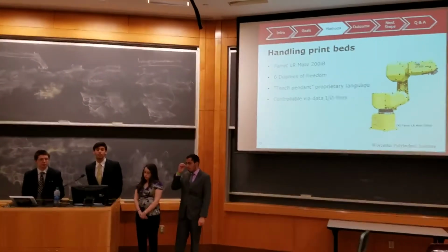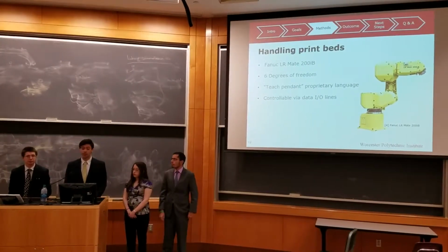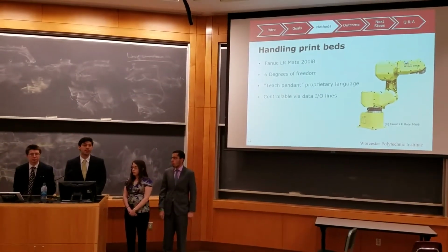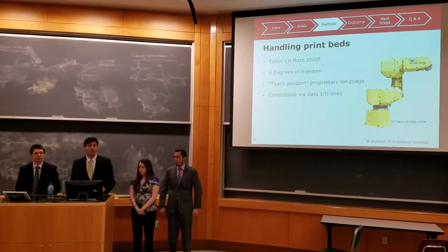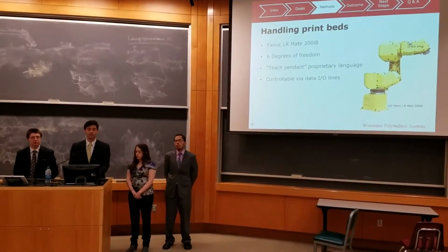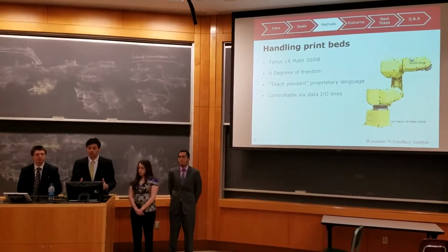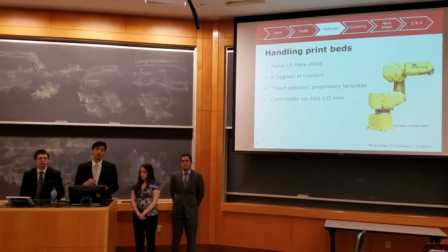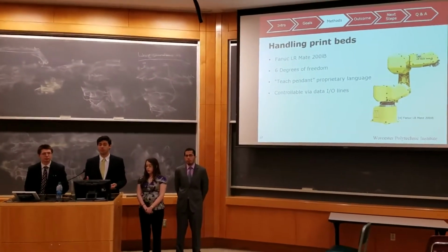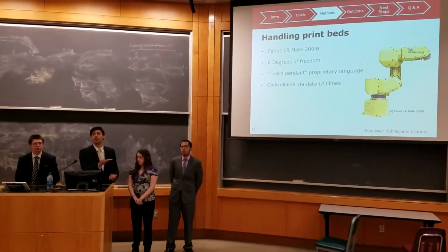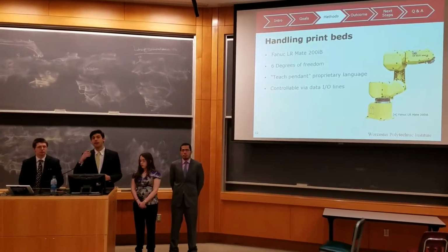So how we physically handle the print beds, this was a small mechanical electrical engineering problem. We had available to us a FANUC LR Mate 200iB, a late 90s 6-degree of freedom robotic arm. It uses a proprietary language on a teach pendant, and you can do offline programming, although it's just easier to be in person having this pendant in your hand. You can manually jog the robot around, set a position, and actually how I programmed it was one set of motions for going in, picking up the plate, turning on the electromagnetic solenoids to make sure the print bed doesn't move around during motions, and then dropping it off.